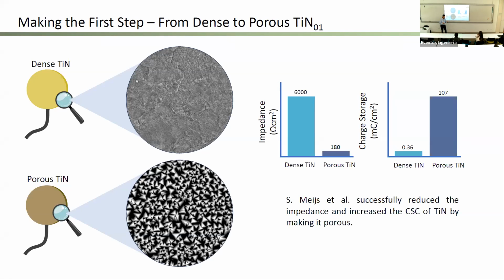Why? Because by increasing the surface area, we're increasing the electrochemical double layer at the surface, and this titanium nitride, which is over stoichiometric, which is rich in nitrogen, has also some other effects. We call it pseudo capacitance, where at this surface we can have Faradaic charge transfer, which also contributes to an increased capacitance. So TiN is a supercapacitor. It benefits from the electrode double layer, from the Helmholtz layer, and also from Faradaic reactions.